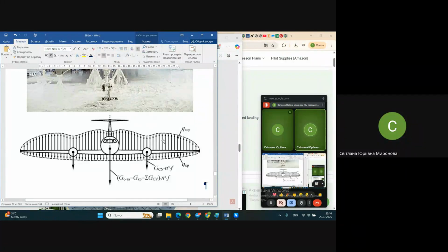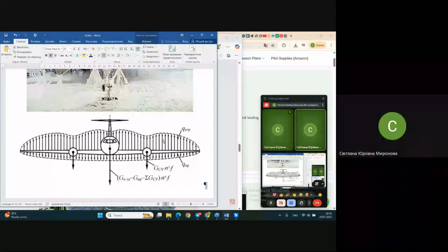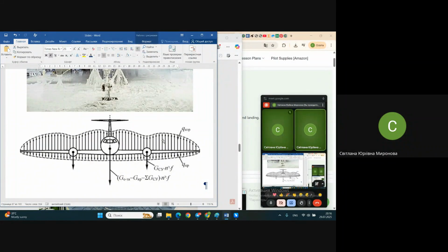And in addition to the weight, we have one more type of load, aerodynamical loads. Weight, aerodynamical loads, and maybe some additional loads depending on the type of aircraft, if it's a supersonic aircraft with very high speed. Some loads may be the result of aerodynamical friction and thermal changes. Plus, during evolutions of the airplane in flight, we have inertial loads, and so on.